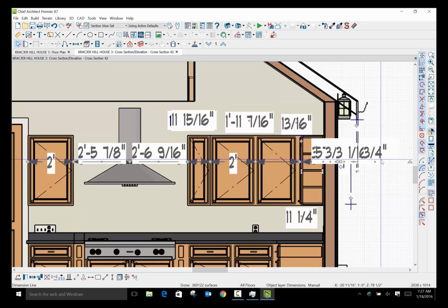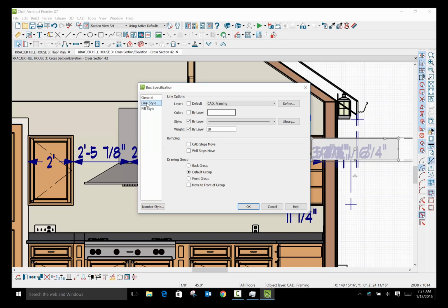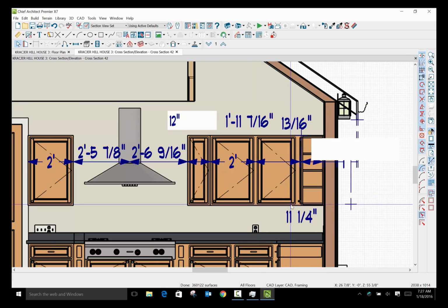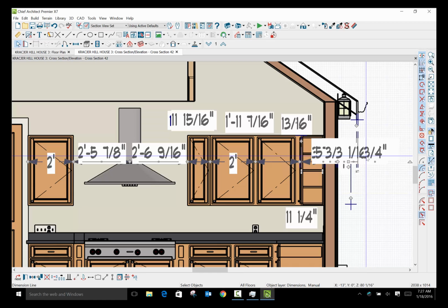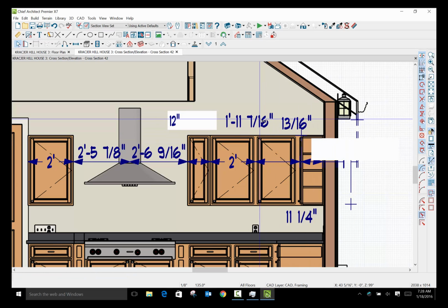And you want to make sure that whiteout square is in front. So you go back here to the line style. We want it in the front group, and it'll cross out all that stuff, like that. And all we really care about is what's really happening here. We really want this to be 2 foot as well. So what we can do is, again, just take this whiteout, tab, copy it, Control-C, Control-V, and just white all this stuff out.